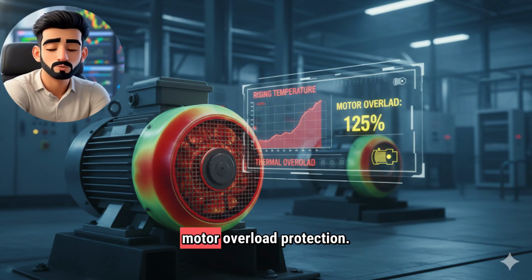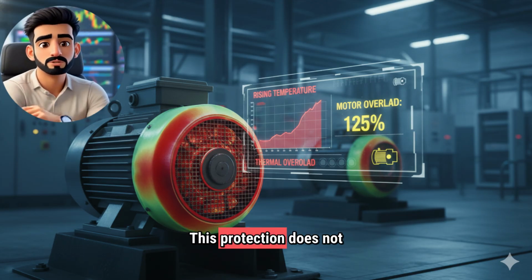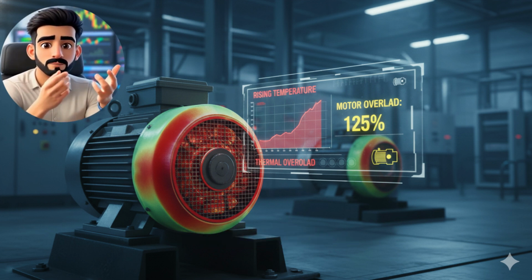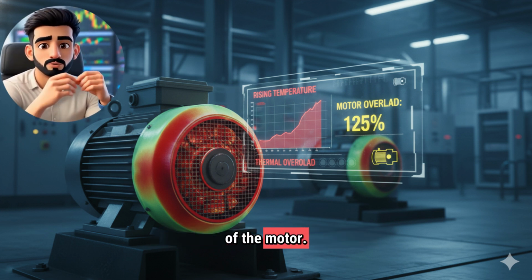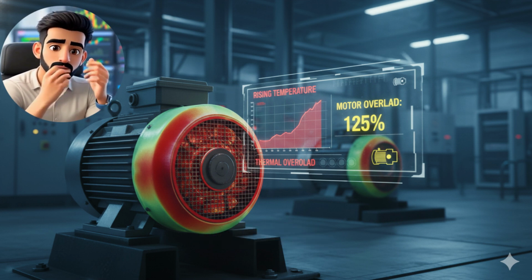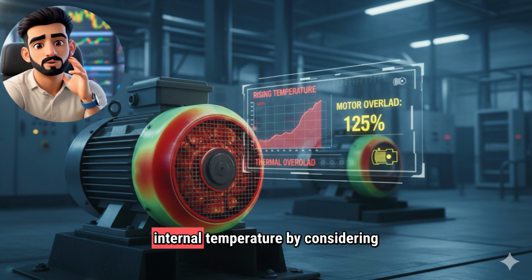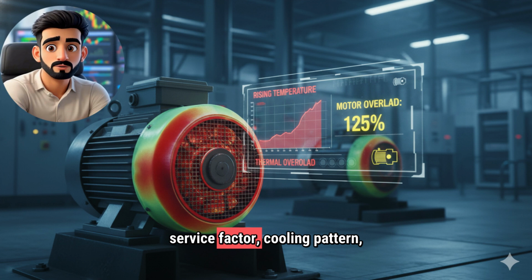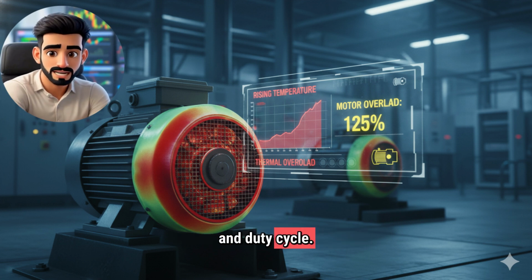Now let's talk about motor overload protection. This protection does not make decisions solely based on current. Rather, it approximates the thermal behavior of the motor. Inside the VSD, there is a motor thermal model. This model estimates an internal temperature by considering the motor's rated current, service factor, cooling pattern, and duty cycle.